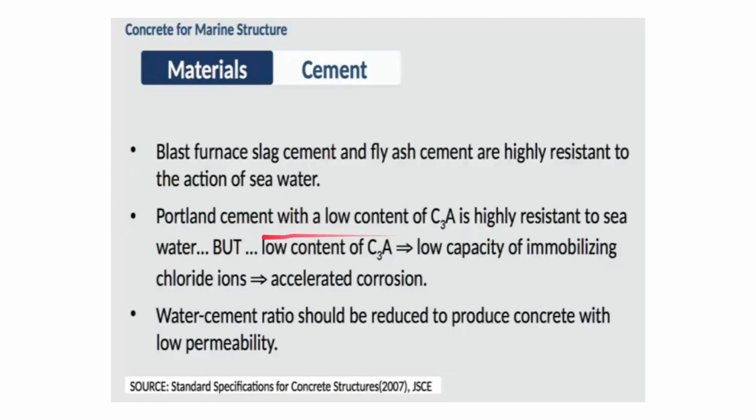Okay, that comes with a problem: low content of C3A will result in low capacity of resisting chloride ion intrusion, and that will lead to accelerated corrosion. So on one hand, lower C3A is highly resisting the seawater, and on the other hand, it is again increasing the chloride intrusion. It is not stopping the chloride ions, so that is resulting in accelerated corrosion. So there is plus and minus both together.